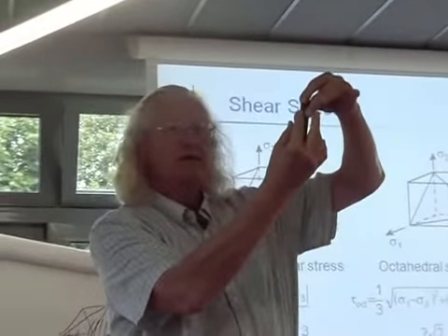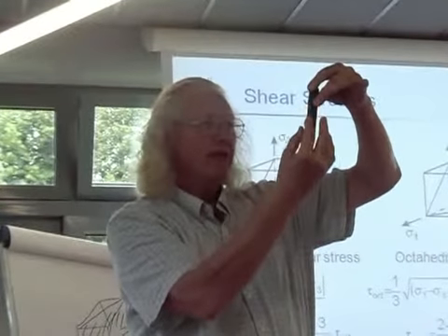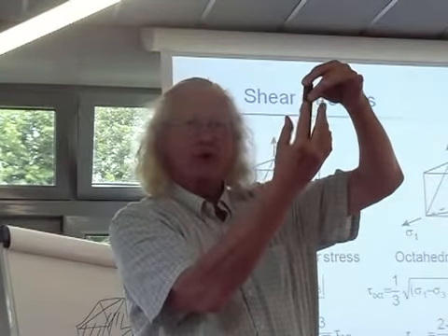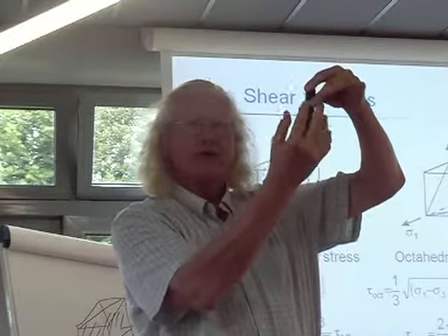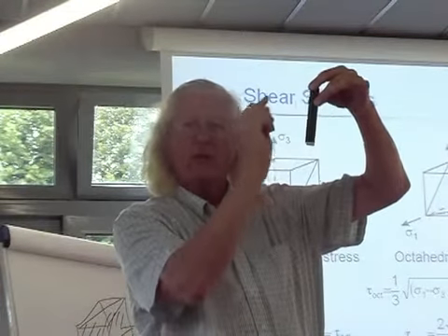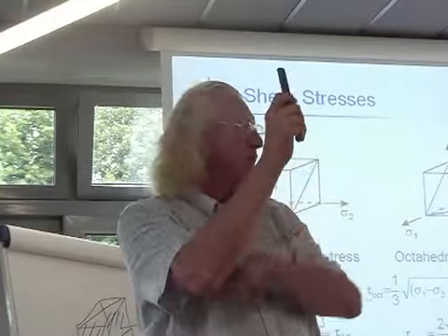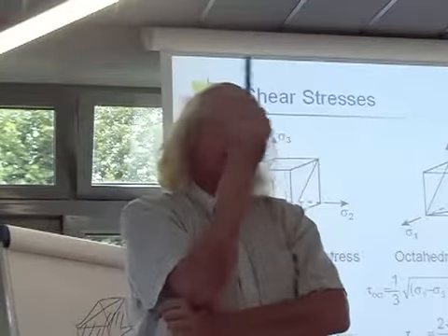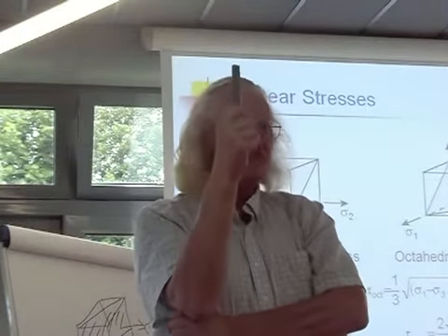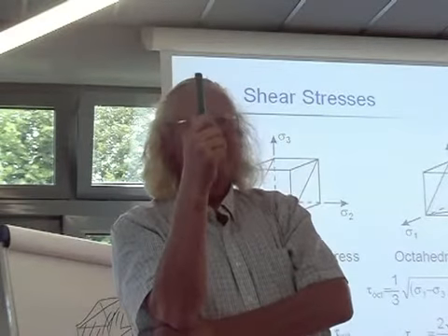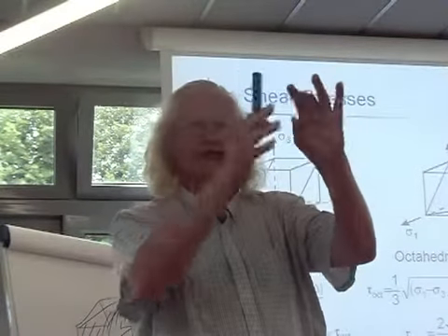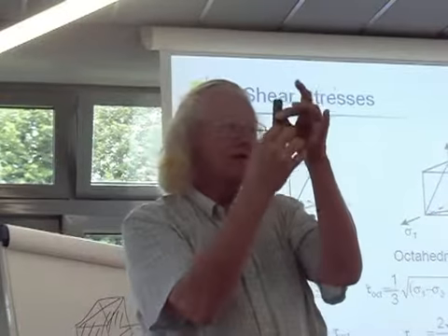So if I have to yield many, many grains, then some kind of averaging process is a better measure than the maximum stress in just one of these grains. So you find for plasticity and yielding, the Mises stress works very, very well, because you need this smaller stress, this averaging stress of many, many grains.